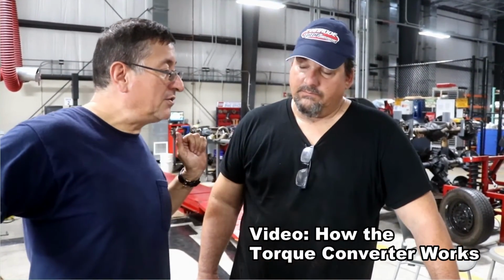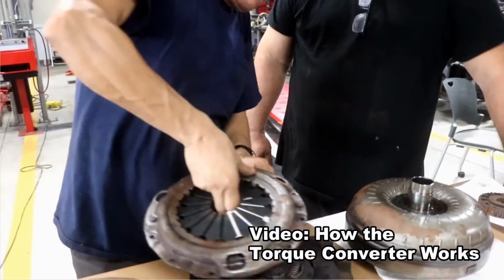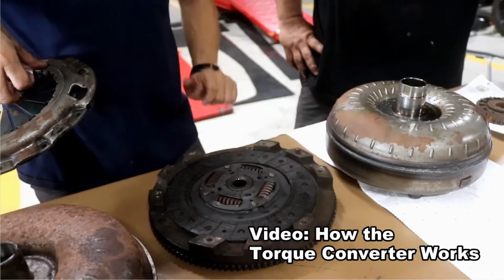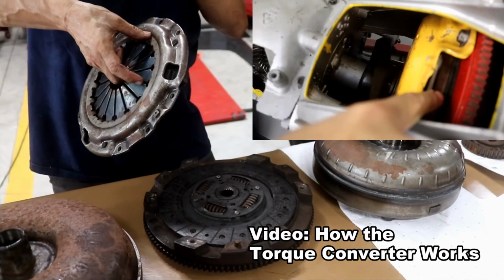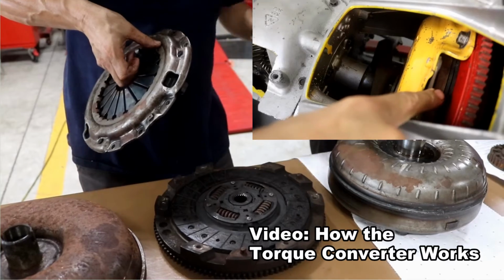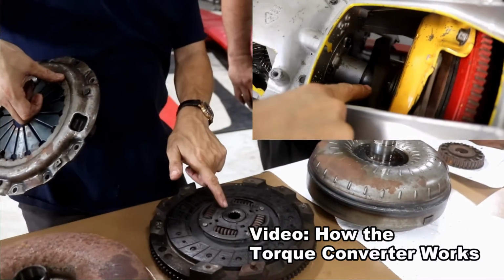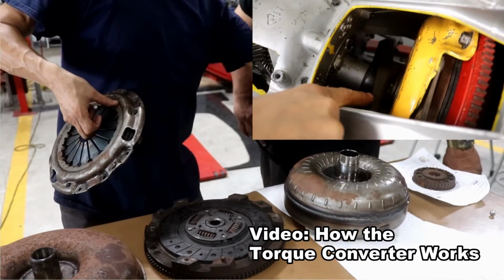But when you release the clutch pedal, this element, the metal pressure plate with the friction material, connects with the flywheel. Like in the video that you have on the screen, when you release the clutch pedal, the pressure plate, the friction plate and the flywheel are connected together. In other words, the input shaft of the transmission right now is spinning at the same speed as the crankshaft of the engine.